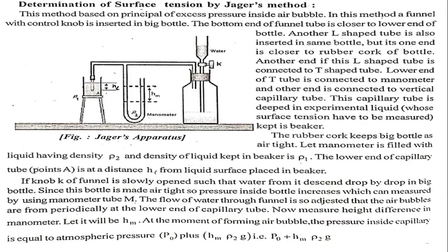At this end there is a manometer. See here the tube, here connected a manometer, and manometer consists of liquid having low density. At first limb of manometer and second limb of manometer, the difference between the liquid level in both is measured by the help of scale. See in figure.